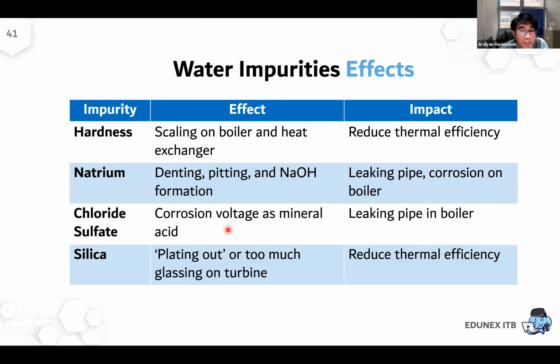This effect or impact will not occur directly. Like if you use hard water or use a high content of silica in the water, it's not that you use it once and then the boiler will break. No, but it will happen eventually, in the long term. But once it happens, the remediation, the repair, will be very hard. The effect will be very, very severe, and you need a lot of money to repair the damage.